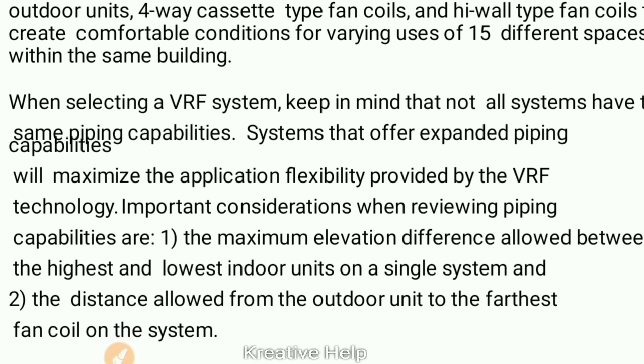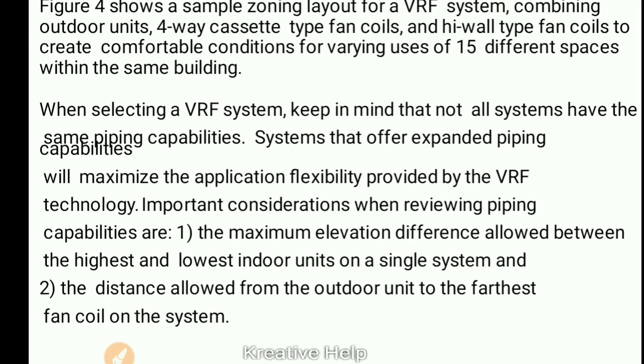When selecting the VRV system, keep in mind that not all systems have the same piping capabilities. It is important to review the maximum piping capabilities, such as the difference between the highest and lowest indoor unit on a single system, and the distance from the outdoor unit to the fan coil unit.